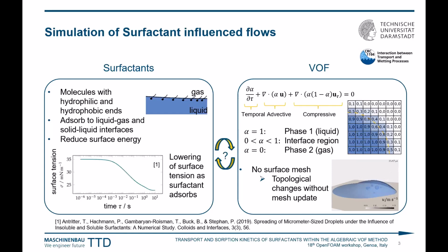Then the idea is, how do we relate these two aspects? Because as I talked about, surfactants are basically a surface dominant phenomenon, meaning whatever adsorption or even the phenomena of transport can be wholly identified by a quantity which is at the surface, meaning per unit area. Whereas in volume of fluid, if you want to solve mostly a scalar transport equation or even any field, it is per volume. So somehow we need to have a connection between these two.